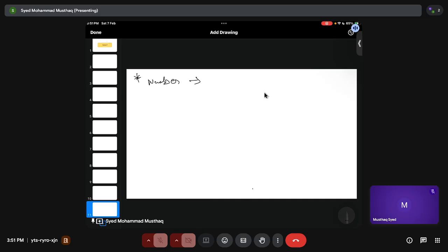Depending upon that number, a sieve is nothing but a cross grid of wires of a certain shape, and because of these cross grids you have apertures, right? You have some holes, and these holes have a certain size. The standard of the sieve is that each sieve has a certain number, and depending on that number you have the size of this aperture.